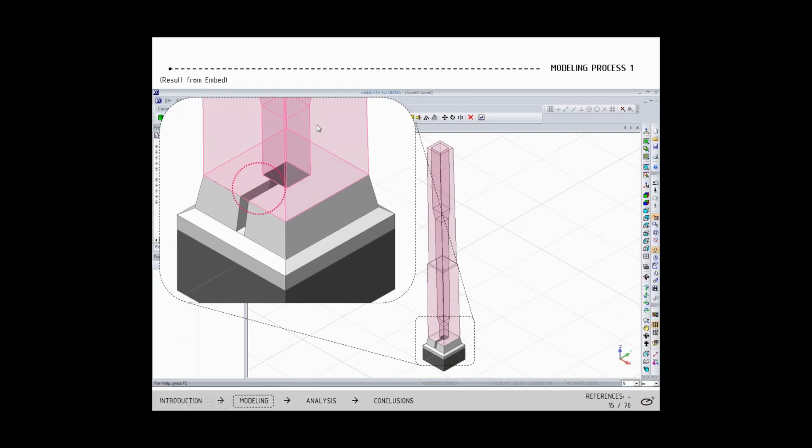If we don't print them, when we generate the mesh, these lines will not be generated on the solid, and this fact can lead to calculation errors. So what we should do is to use the command embed again to print the lines on the adjacent solids. As I said, it is incumbent to do so, since the meshing will be made correctly.